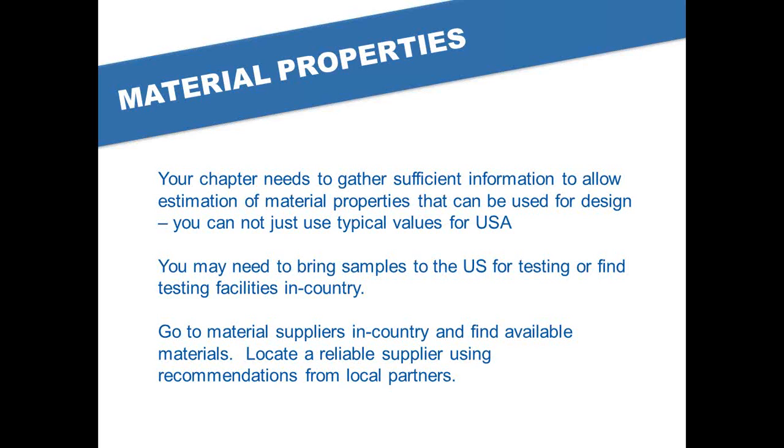recommendations from your local partners, the community or an NGO, about in-country suppliers, and you'll go there and find what's available. And say for reinforcing bar, you may even want to buy a length of it, have them cut it into specimens that you can bring back to the States and go ahead and test them here.